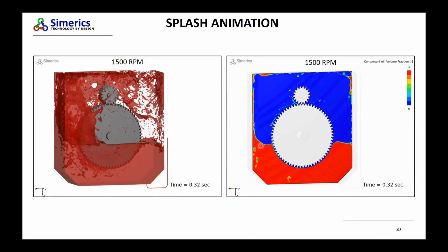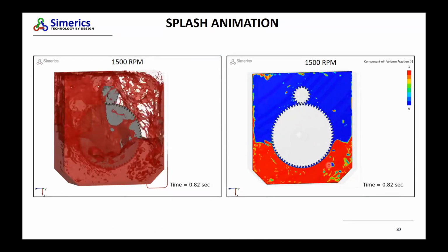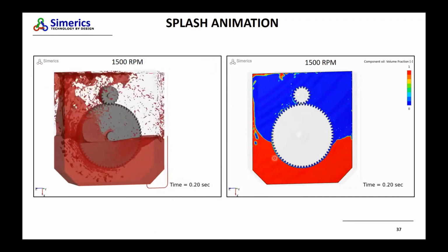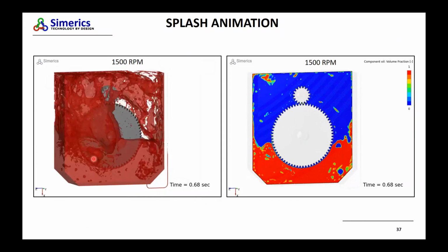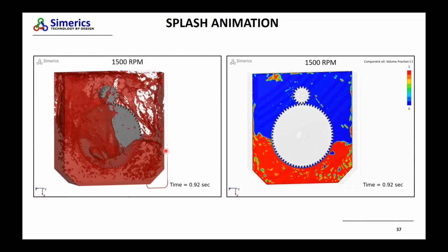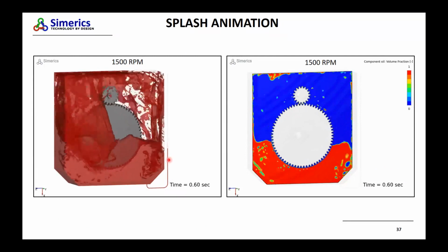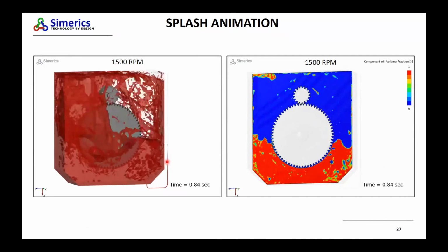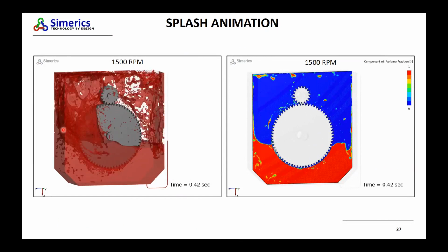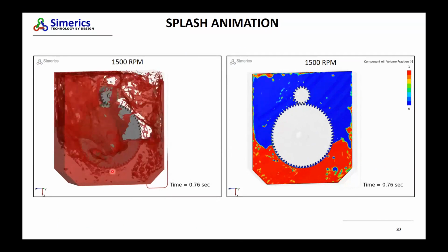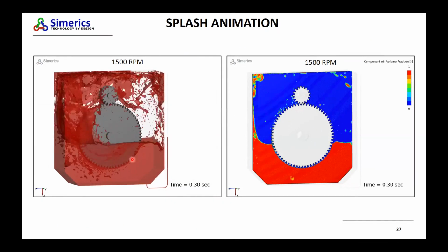What we notice is there is a level of oil in the beginning. It gets disturbed and the level drops because some amount of oil goes into transit. But that oil makes its way back and it becomes quasi-stable. If you look at this pitot tube, if you run it for a while, the pitot tube becomes quite static, it'll just keep oscillating about this space. And then you will notice there is a quasi steady state behavior where a fixed amount of oil keeps rotating in the system.